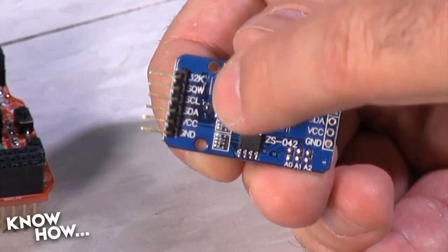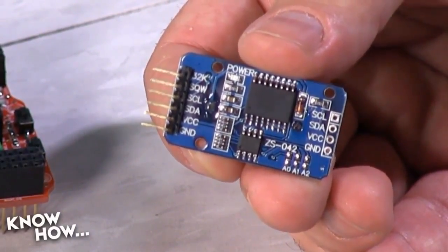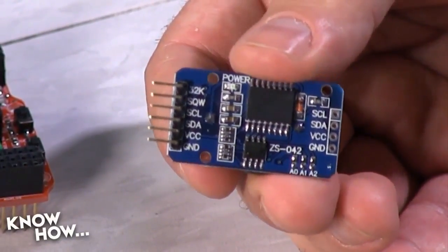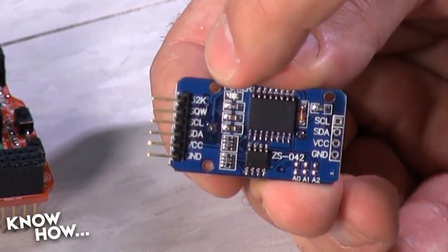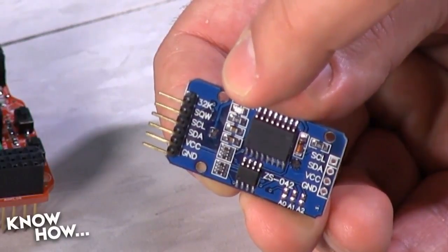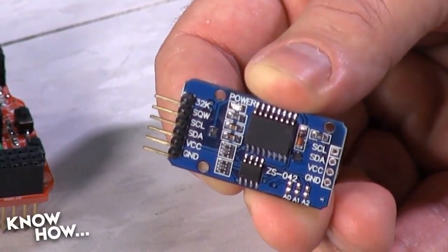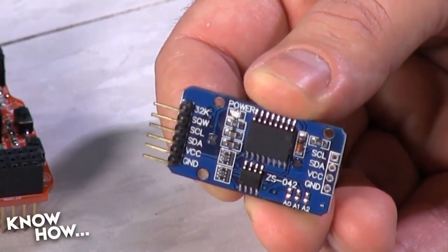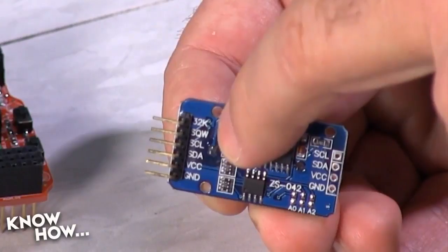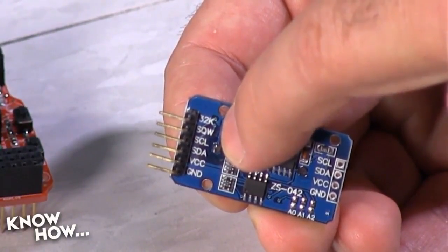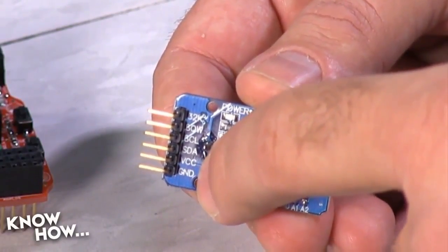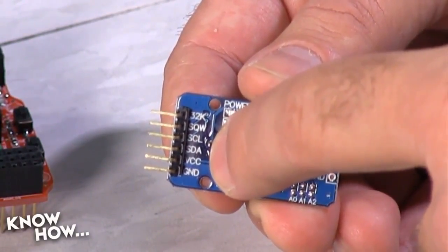And then we have similar pins over on the other side. This particular real-time clock module just has them on both sides for convenience. There are 2 other pins on top here. The 32K is a very precise 32 kilohertz output that you can use to drive other counters and whatever else if you need a very precise clock. We're not going to be using that. And then the SQW, I'm not entirely sure what that is. I think that stands for square wave. I think that's a pulse per second. Yes. Again, we're not going to be using that. All we care about right now are the power and the serial clock and serial data pins.